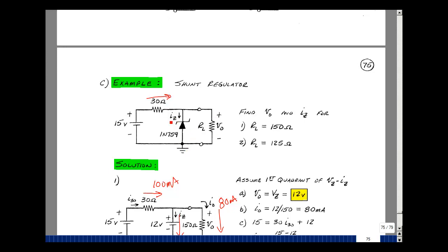The power dissipated in here is the product of the voltage and current. And that varies depending on what's going on out here. The worst case is when you take the load off, all of that current flows into here. And these are Zener diodes and a shunt regulator.